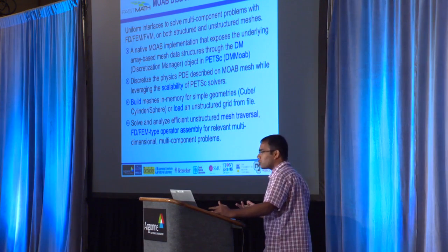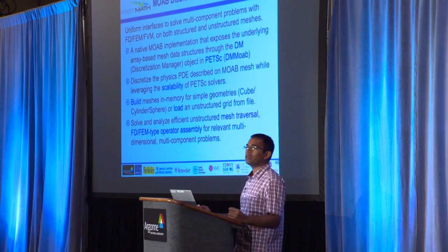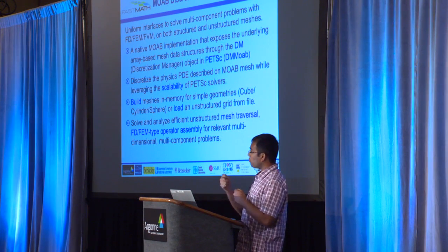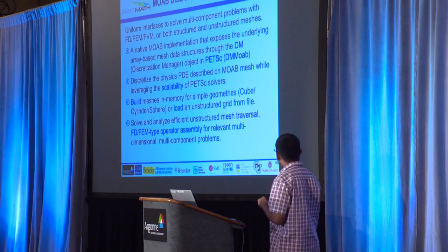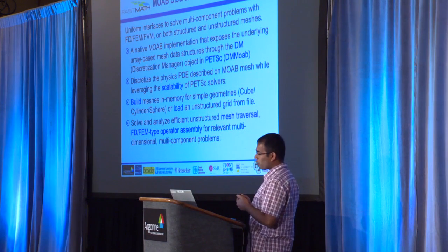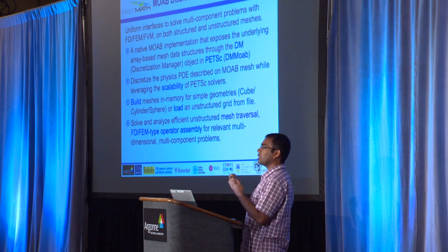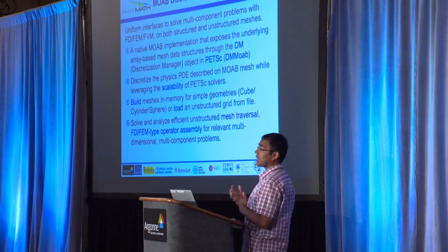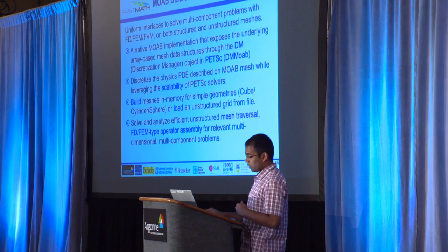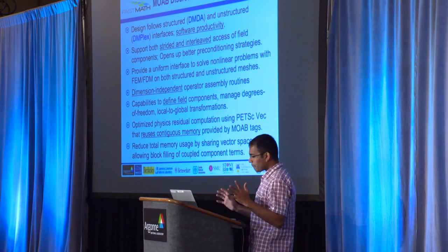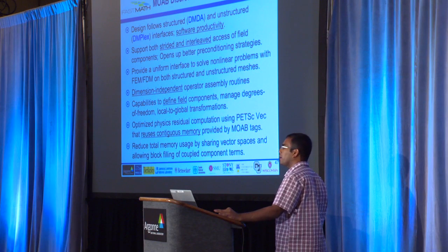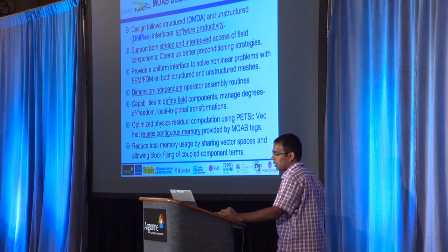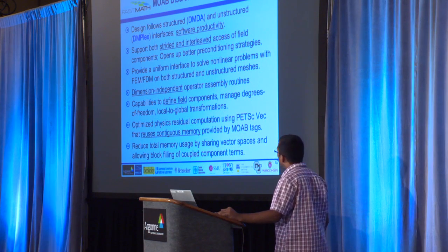It also provides an infrastructure where you can play with different types of assembly techniques and mesh traversal techniques, especially since Moab is array-based. It provides options for optimizations on how you want to do the finite element assembly of your operator. So it provides a framework where you can play around with a lot of different options, especially with the PETSc command line infrastructure.